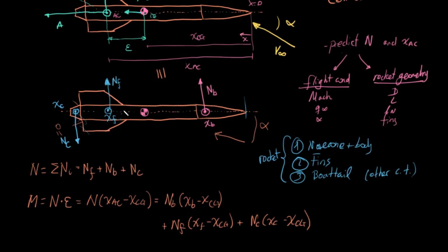So we have fins, and we have them on the rear side, as far back as we can, because if we put fins here, where the aerodynamic center of the fins is practically, let's say, 25% from the tip, this would be the aerodynamic center of this pair of fins, and these fins would destabilize.